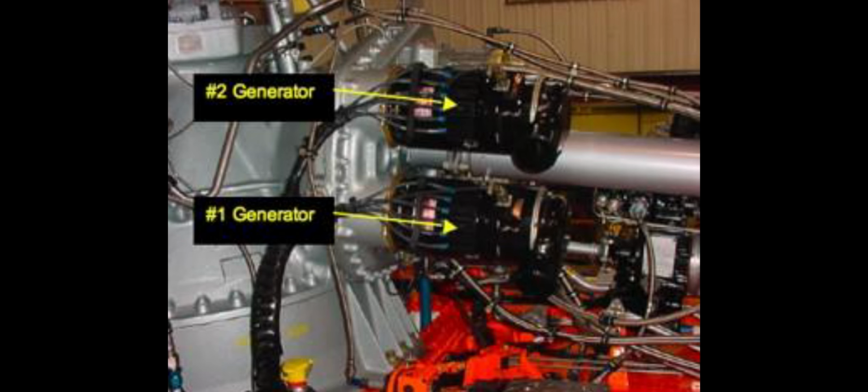Component description: generators. Two brushless generators driven by the main transmission accessory section provide three-phase AC power for aircraft equipment operation. Each generator is rated at 20 kVA and delivers 115/208 volts AC at 400 Hz, three-phase power when rotating at 8,000 RPM.